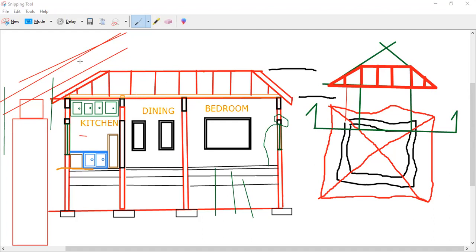Then, after the rafter, you need to add your other roofing details. Those other details include the plyboard, and the type of details that you add is relative to the type of roof. If it's just a simple shingle roof, then you would need to add your plyboard. Above the plyboard, you need to have your underlay, and above the underlay, you'd have your shingle, and that's pretty much it. If it's a smaller type of roof, you might need purlin. If it's, for example, a zinc roof, you might need to add your purlins, or your lats, all those good things. All right, so that's pretty much that for that.